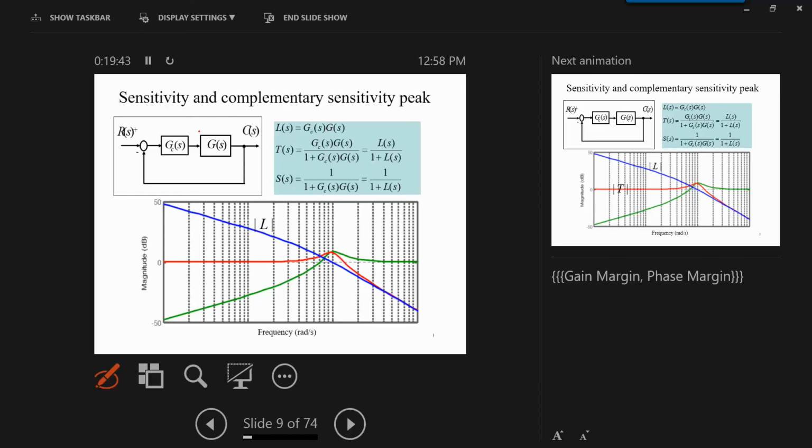So the error transfer function here, what is the system? We have minus 40, this is 1 decade, and if I extend it here, it is more than 2 decades. So this system is most likely a type 2 system, or this is a type 1 system. For a type 1 system, what is the error for a constant input? Zero. Kv is infinity, right? And the error therefore is 0.